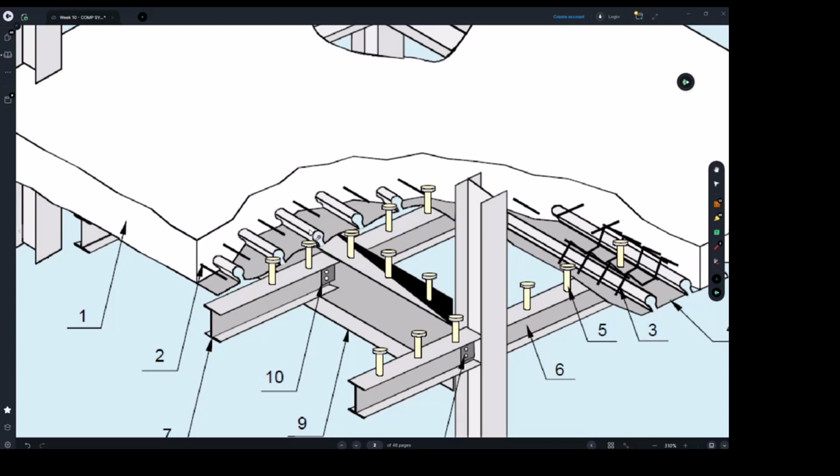Remember, the tension for most of the slabs is at the bottom because they are simply supported, or they've got positive bending. Now, someone is going to ask, what about over the support, where you have negative moment? Well, that's where we put additional top reinforcement. So this is one of them: the slab is in composite with the bonding.